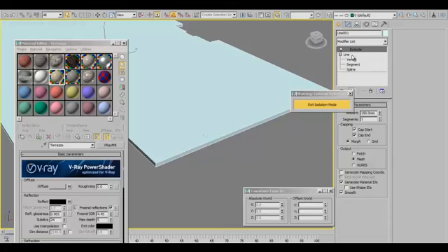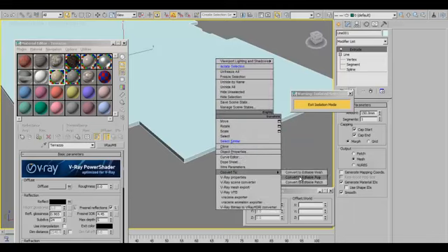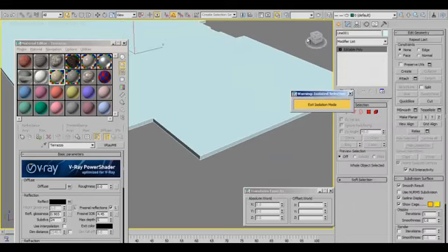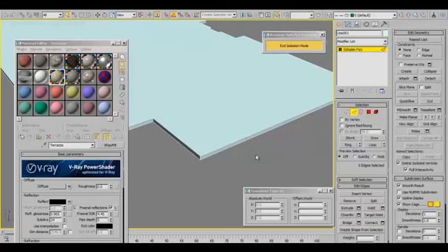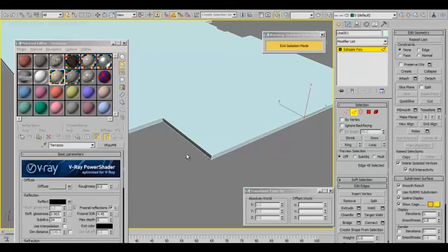Before I do that, this is a spline with an extrude modifier, making it look like a polygon, but basically not truly one. So what we're going to do is convert this into an editable poly, so we can get to the sub-object level mode. And here I'm going to connect, and right here too I'm going to connect.